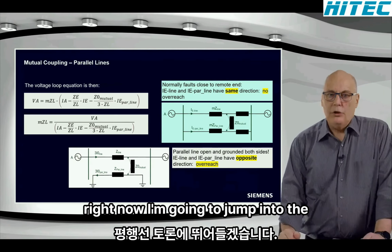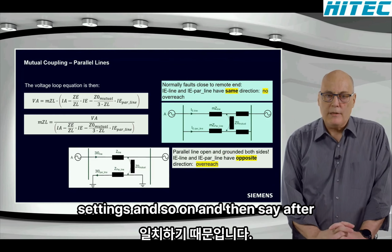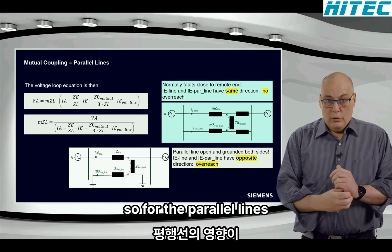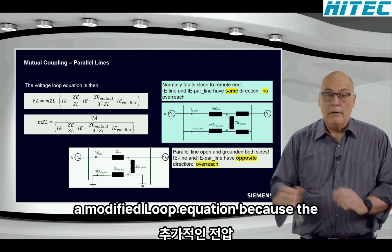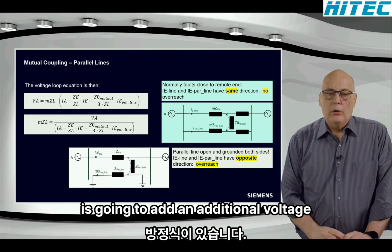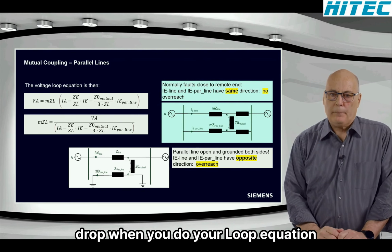Right, now I'm going to jump into the parallel line discussion because it fits in there a little bit with the KR, KX settings and so on. And then, after the break, we'll carry on with the zone grading. So for the parallel lines, there is a modified loop equation because the influence of the parallel line, as shown over here, is going to add an additional voltage drop when you do your loop equation.